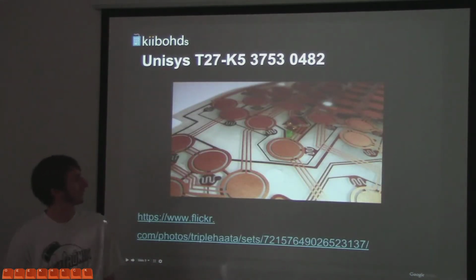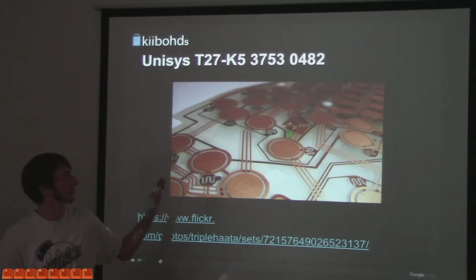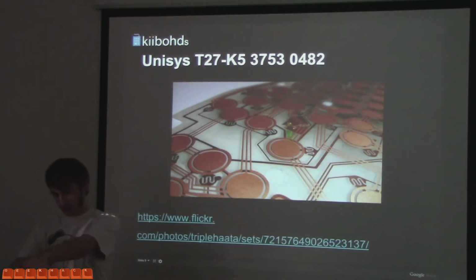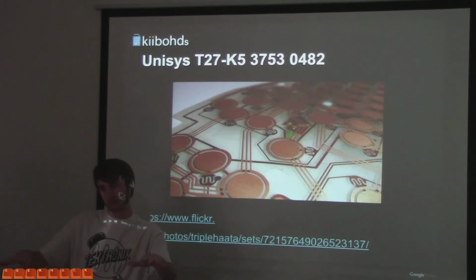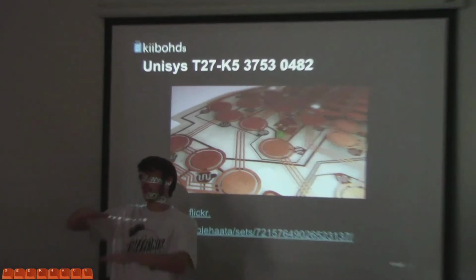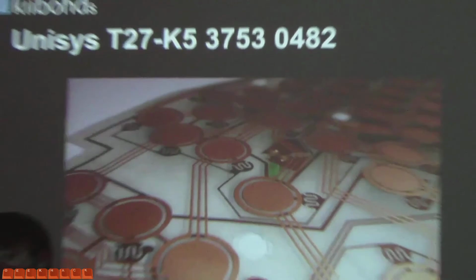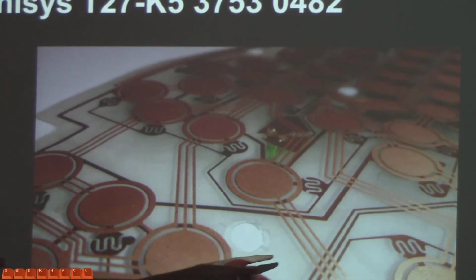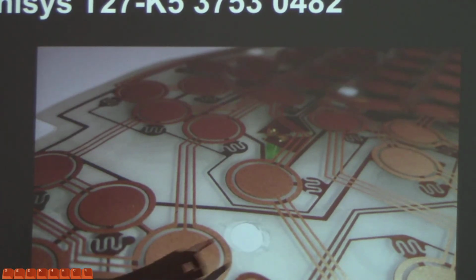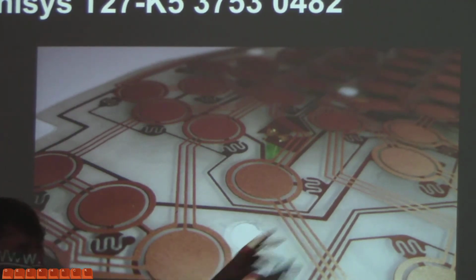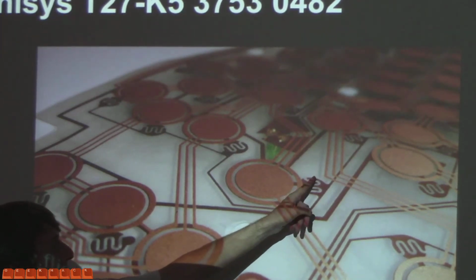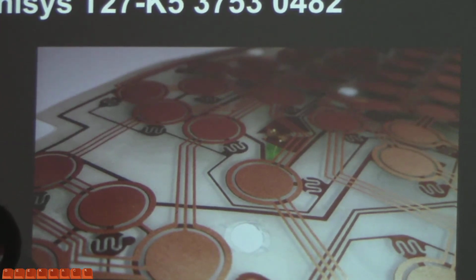So this is a really neat find, I have pictures later, but this is a single membrane keyboard. If you look at the keyboards over there, there's a PCB. This uses sort of the Model M style, where you have a mylar membrane with contacts. However, in this case, there's only one layer. This is printed on both sides of the layer. This right here is typical rubber dome. So you have a graphite pad that goes down. If you bridge the contacts right here, it'll actuate.